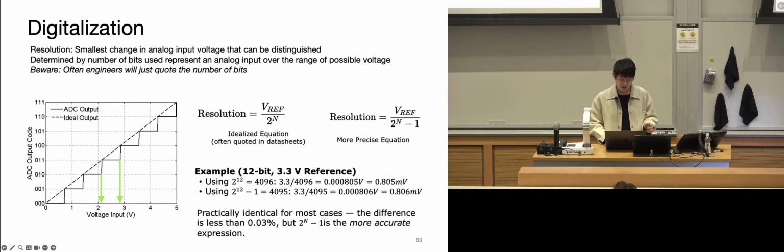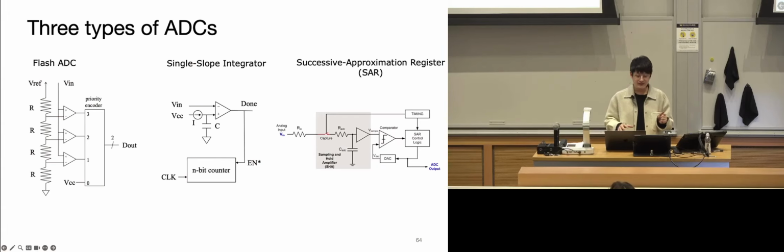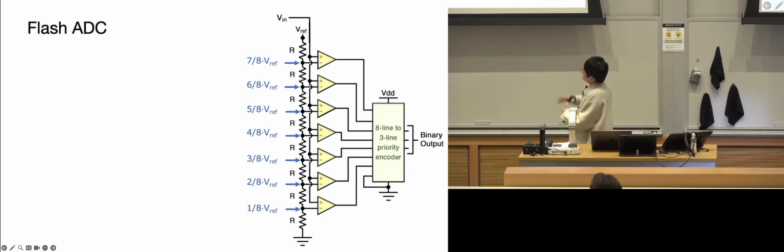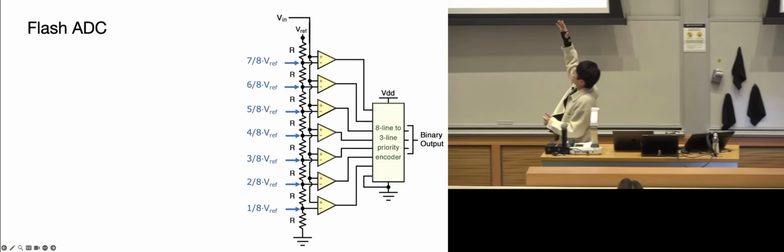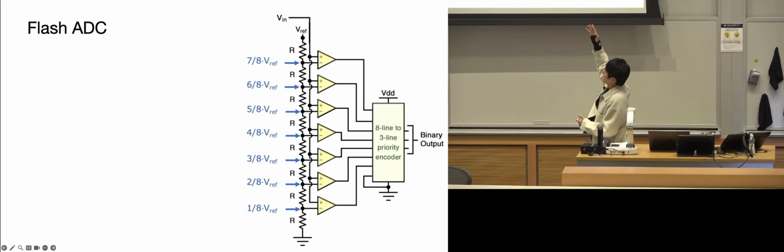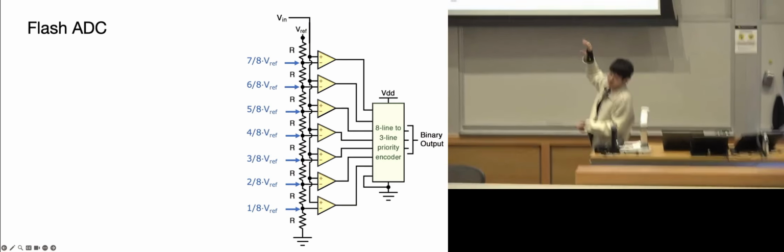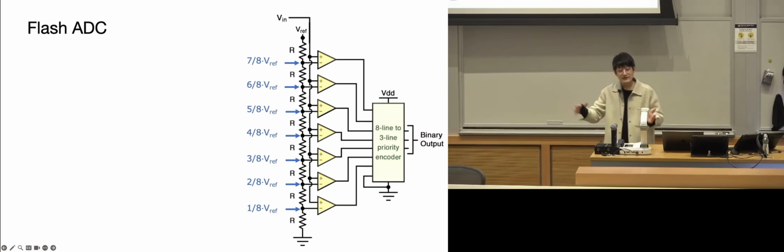Okay, cool. So we talked about 3 types of different ADCs. The flash one, which, as the name indicates, is super fast. It's pretty much a bunch of resistors connected in series, and they are very accurate relative to each other, and easy to manufacture because chances are they're manufactured in one batch.